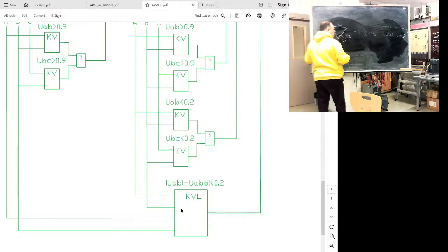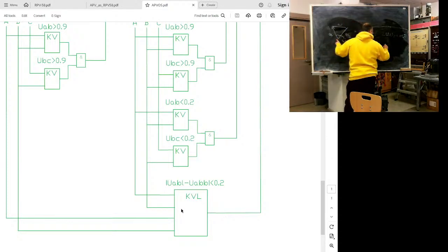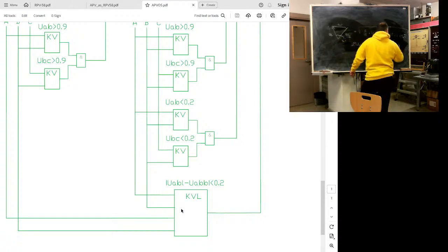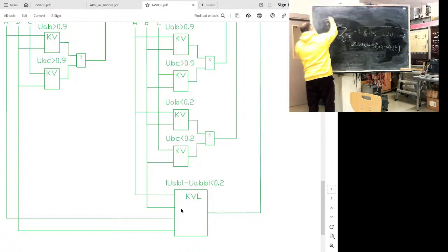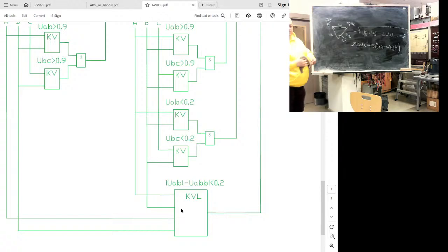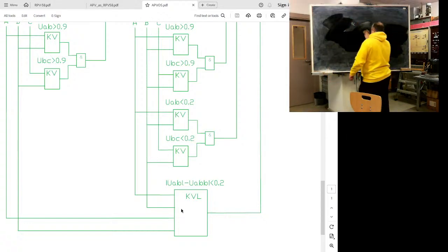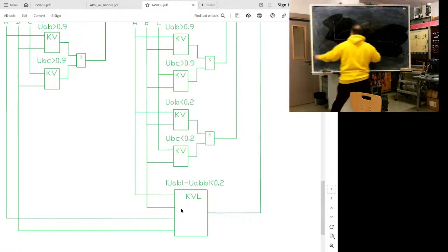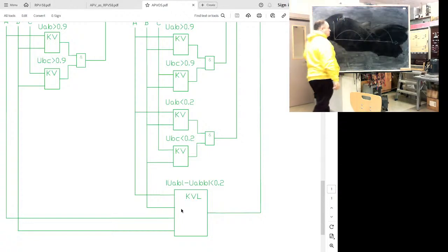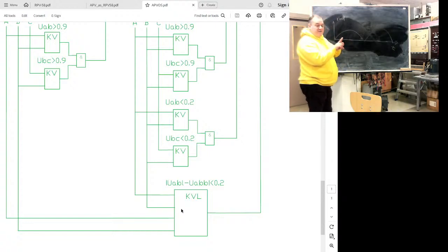If voltages are constant, our variable term is double U1 U2 cosine delta, but what is delta as a function? Omega 1 minus omega 2 times t. That's what's under our root. This one rotates at omega 1, this one at omega 2. We will see the so-called beat. The absolute value will give us something like this. It's the absolute value of delta U, goes to 0. This axis is time, and it depends on the frequency difference.